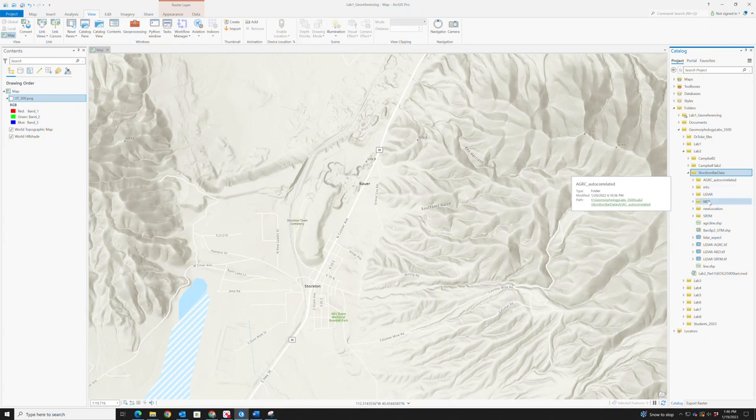The NED is from contour maps, and the LiDAR is from point clouds, hopefully filtered to bare Earth, so they might be better thought of as digital terrain models. And so if we were to difference them, we might see differences due to trees in one image and no trees in another for some of them. So keep that in mind.